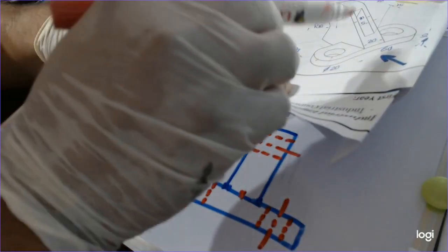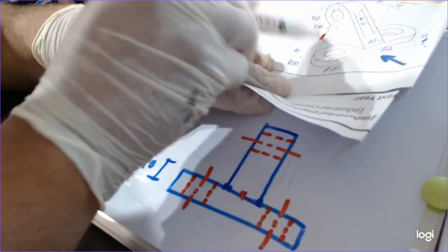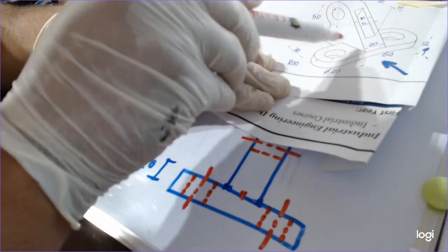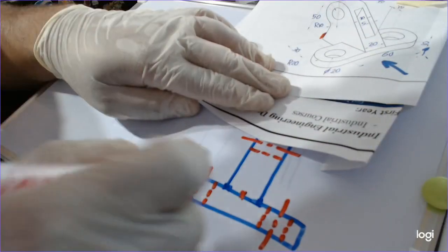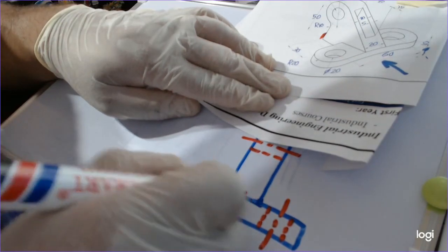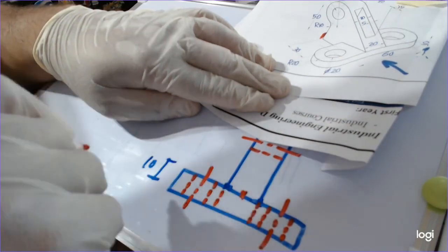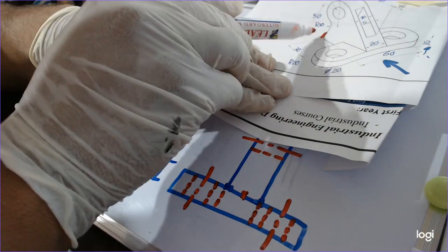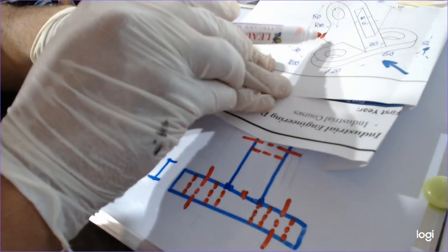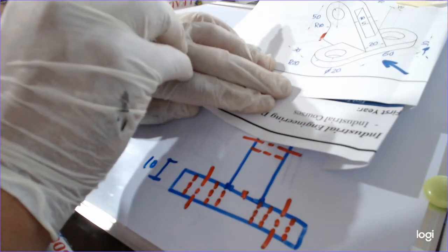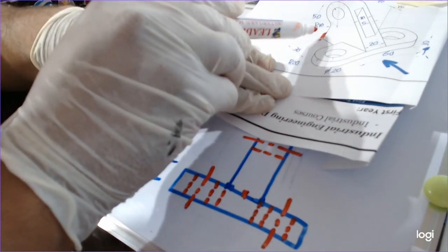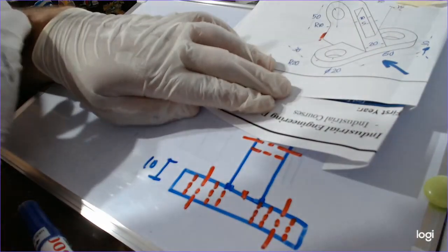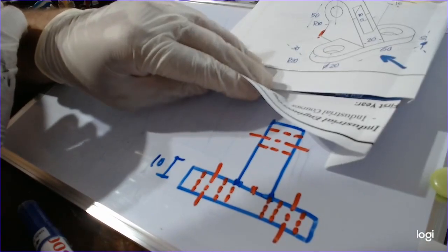So, can you see this part of this line? Actually, this part of the line continued on the back side of this space. That means that it will continue as a dash line here and there. Okay, so this is the same thickness of 20 millimeters, and this one continued to the ground here, as we can see here. That means that a portion of 10 millimeters of this line will be dash lines right there, behind the base, behind this slot shape. Okay, then